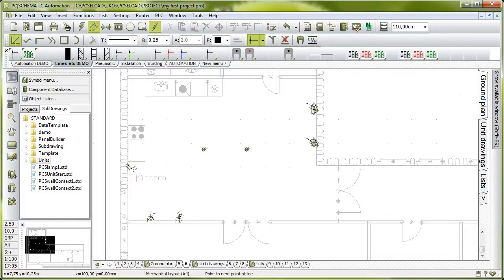And if I want to connect those two switches, I could just draw a line between them, but I would probably need to take the wire from 1.10 meters down to 0 and then up again, because otherwise it would probably be a little bit messy, because I don't have cable trays in my wall at all elevations. So I would direct it downwards or upwards to my cable trays or my cable ducts. But I can take it from here and click here, click to 2.4 if I want that, and then click up here, and then I have placed my cable. So from here to here, and from here to here, and go down to 0 meters, and here to this one. In this way I have got almost correct quantities for my cables as well.